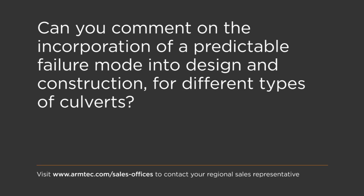In types of failure mode, the most common types of failure will be either hydraulic failure, where the culvert is undersized for current conditions, right? Because we have lots of culverts out there that are currently undersized but weren't at the time of installation. And then there's the durability aspect. So a culvert, over time, if it goes beyond its service life, you get corrosion and you can get loss of steel or pipe material, and then eventual failure.